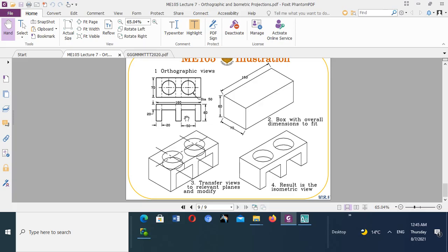And then we will draw this front elevation, which will be these features: square, this is a rectangle, which is a true rectangle. Here it's a whole circle, which makes a true hole. Here two through holes, here two through slots. And then that makes our isometric.